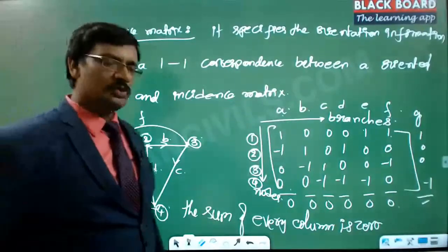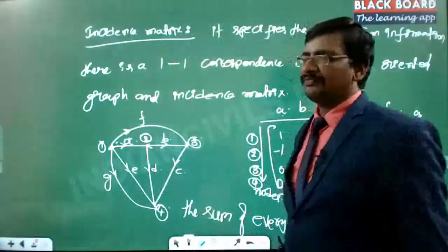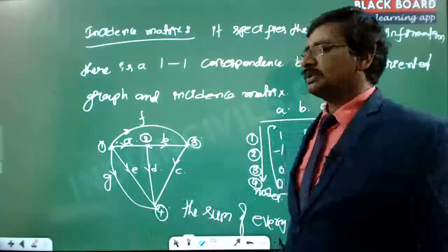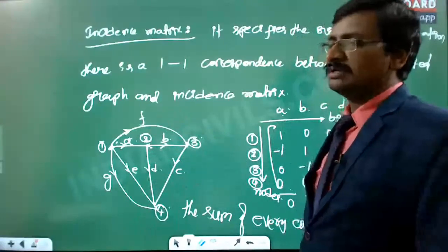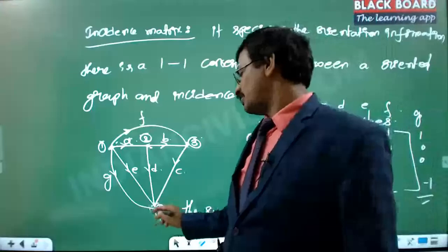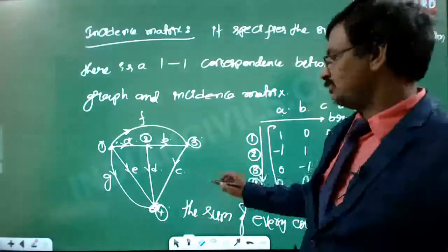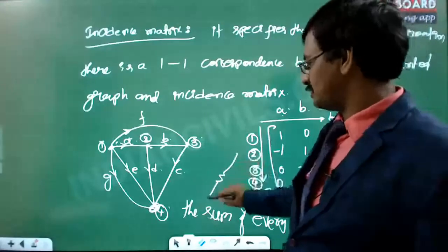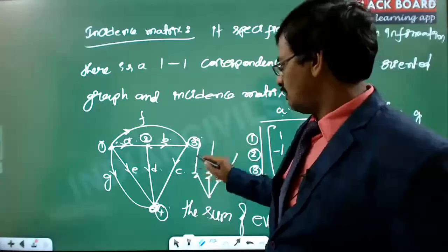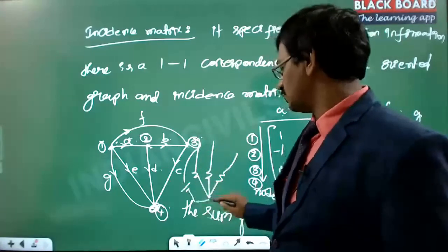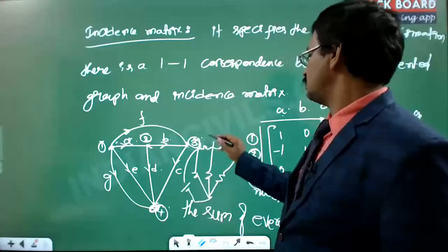Usually, if I ask you to solve a network, say I have connected a voltage source here, and then these are the resistances, and everything is treated as resistance, then we always take one particular node as the reference or ground node. Suppose I put the same thing in terms of resistances like this, and between them I have connected a voltage source, and then there is one more resistance here, and one more resistance here.